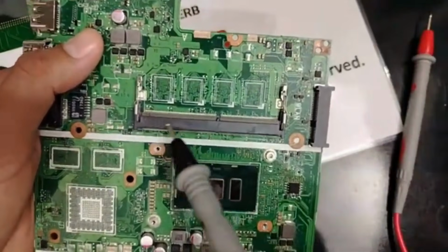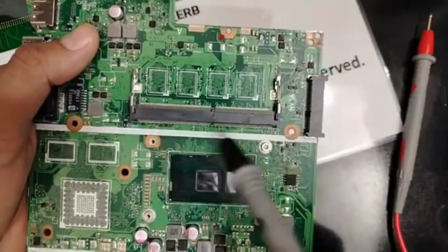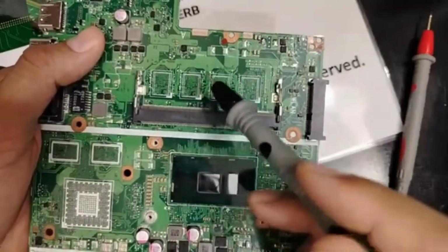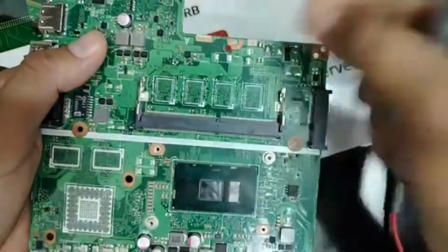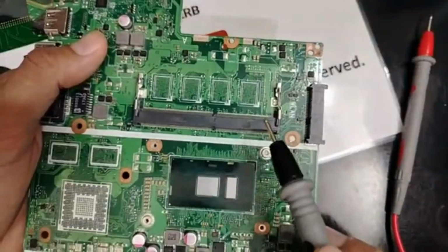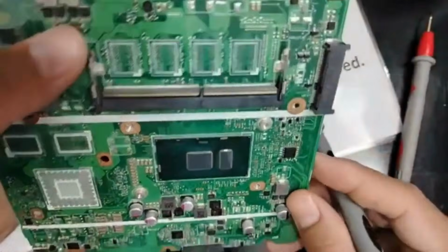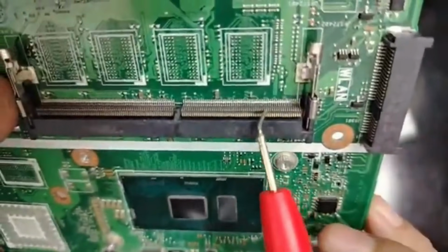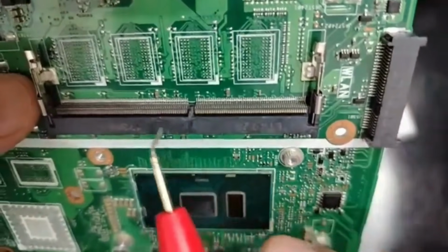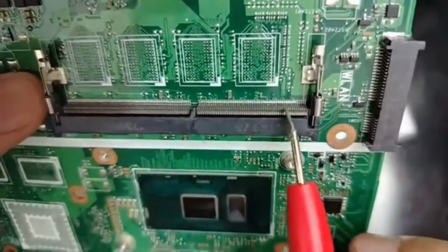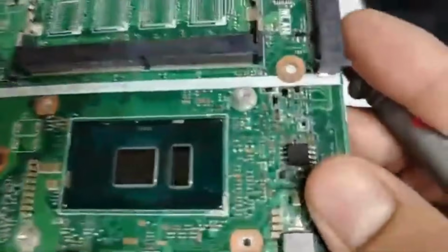Means the short is the RAM slot. The short is in the RAM slot. If we have a RAM chip, it could be shorted, but once the RAM chip is disconnected, means the short is in the RAM slot. Guys, let's check this RAM slot. Let's check the RAM slots. If we check it, we have to find a short here,